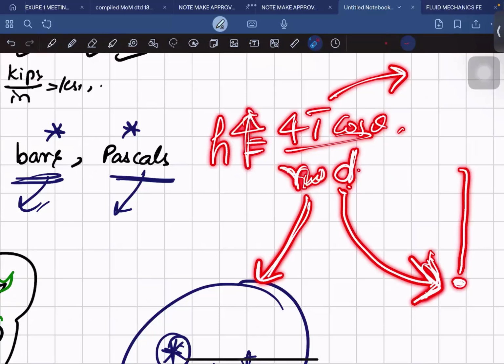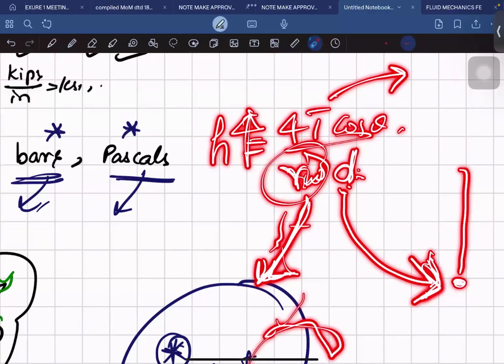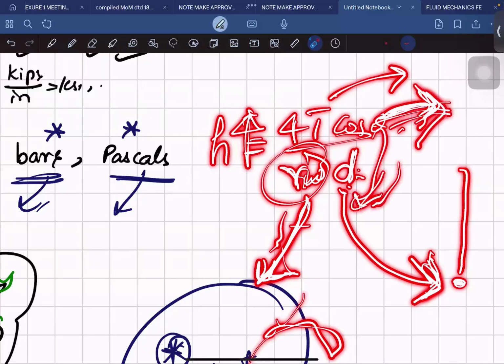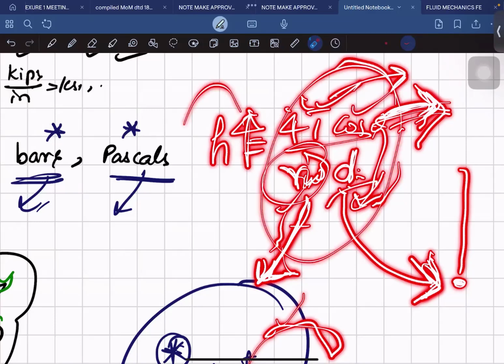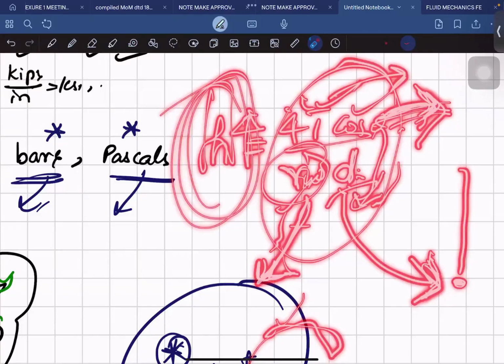And if instead of water there is mercury, there will not be capillary rise, there will be capillary depression actually. The mercury level will come down. It also depends on cos theta, that is the angle of contact, because of adhesion. Adhesion is nothing but attractive forces between two different materials, as one of the friends has mentioned. So it depends on many parameters, four parameters, for the height of the capillary rise.